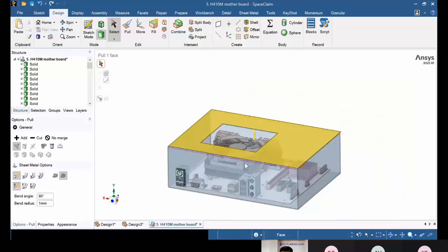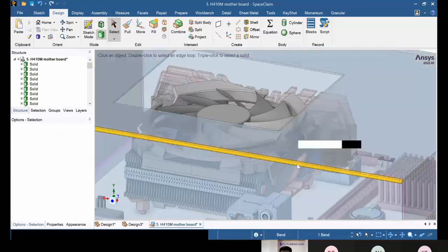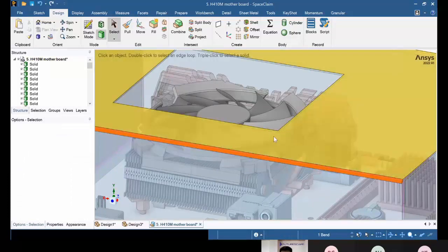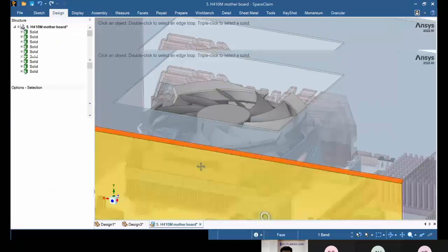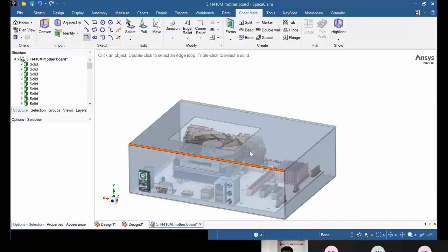Now if I want to, instead of having this band in here, I want to change it and have something else. And just go to sheet metal. So I can just do sheet metal, change the junction type to no overlap.